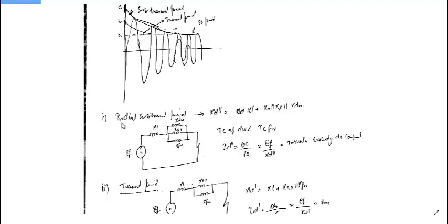So this initial period is known as the subtransient period, and XD double dash is the total reactance that is provided by the synchronous machine in this period, known as subtransient reactance, and it is equal to XL plus XAR, XF (field winding), and XDW (damper winding) in parallel.